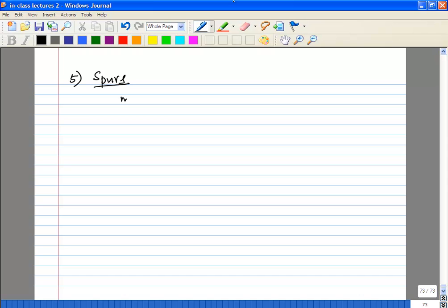So in general you will get components at m omega RF plus or minus n omega LO, for all values of m and n, up to the highest harmonics available in terms of linearity of the mixer or in terms of the harmonics coming in. In general, this is very tedious to analyze, so normally you let the simulator do it.